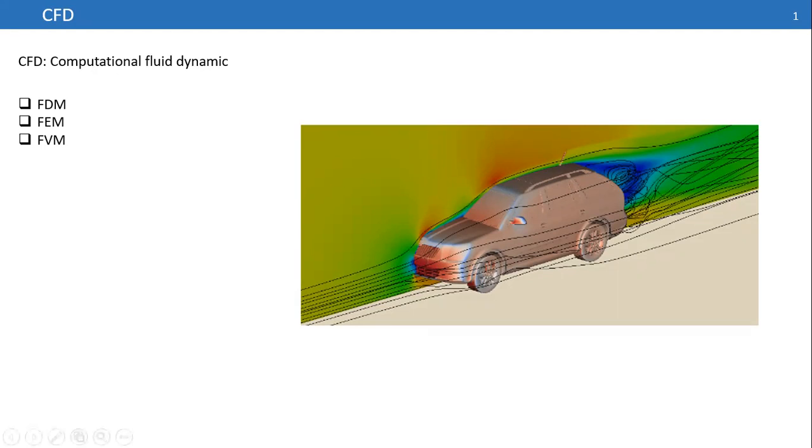When you are using CFD, you have equations known as transport phenomena equations, including the momentum equation, the mass transfer equation, and heat transfer equations, and sometimes you add more, such as Maxwell equations, and you solve them all together to calculate the profiles of your dependent variables.